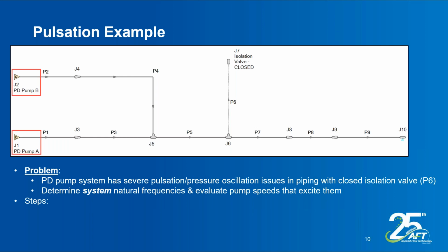So the steps that you will do to accomplish this is, first, you're going to have to ring the system. You smack it with a mathematical hammer, and that's what will excite your acoustical frequencies. If you remember the video of the guy with the buildings, that mathematical hammer is when he would grab one of those buildings and pull it back and let it go. That's the mathematical bump that we are giving the system to figure out what the natural frequencies are.